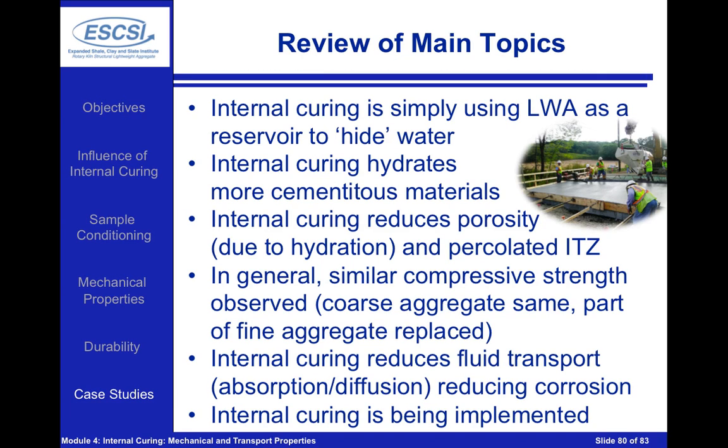So what I really want to do now is try to wrap up and highlight the main topics that we've covered throughout Module 4 here. And what we've focused in on is the fact that internal curing is the use of lightweight aggregate. Typically it's going to be the fine lightweight aggregate that replaces a portion of the sand, and this will act as a reservoir to hide water inside of our concrete.